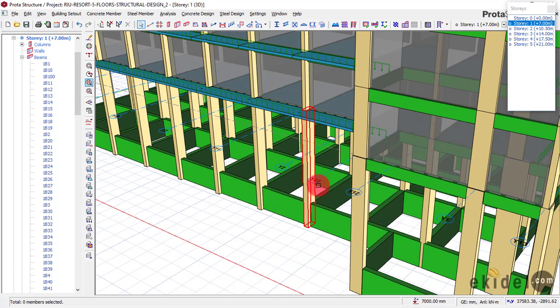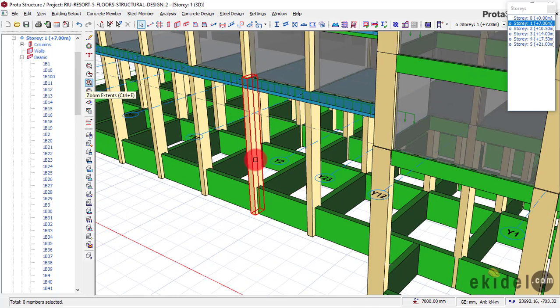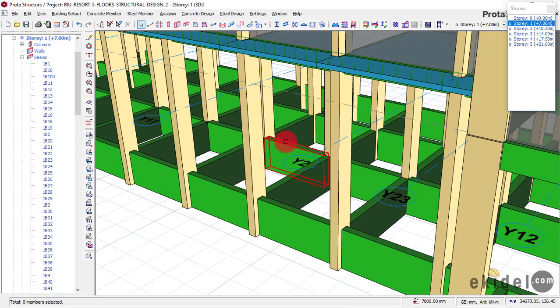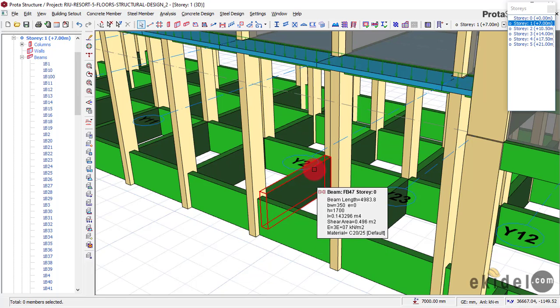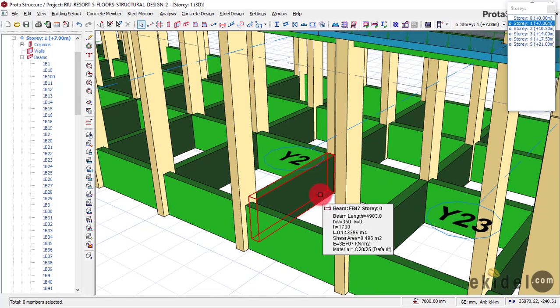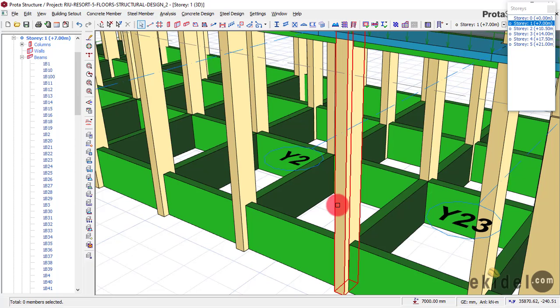How you insert your slab on your Raft foundation is that when you're doing a beam Raft foundation, the slab is meant to be at the top of the beam, and not at the bottom of the beam. So the space between the soil and the top of this beam, or between the bottom of the beam and the top of the beam, will be filled with a sharp sand, or let me say a river sand.